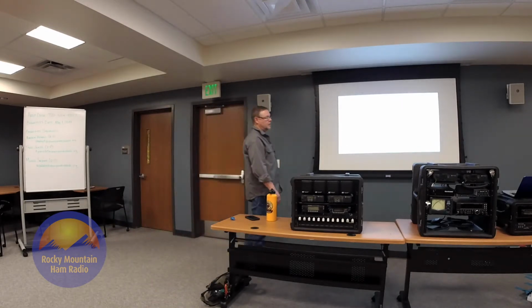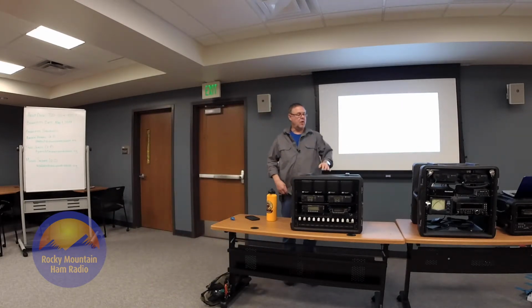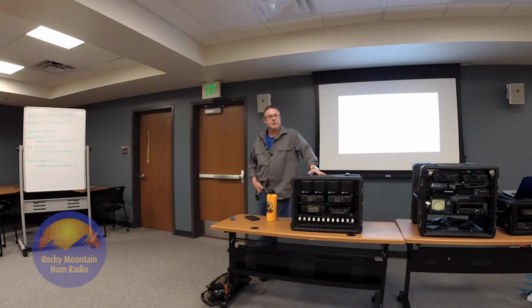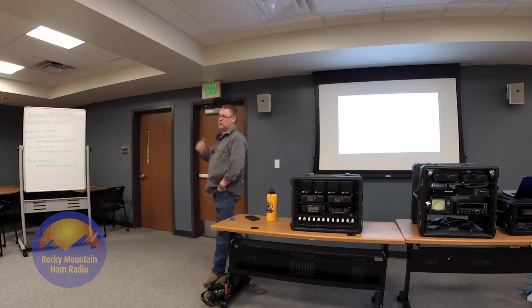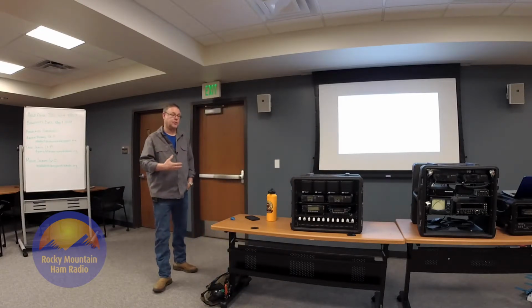Remember the wire sizes are governed by amps, the ability to carry amps. 12 gauge is generally good for 20 amps. It's really good for about 23 to 24, but we keep it at 20 amps. 14 gauge is 15, 10 gauge is 30. You can pull 35 out of it though easily before it starts getting warm. But keep that in mind when you're designing your power system.